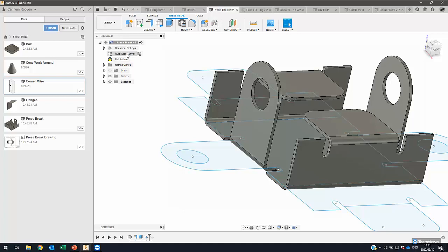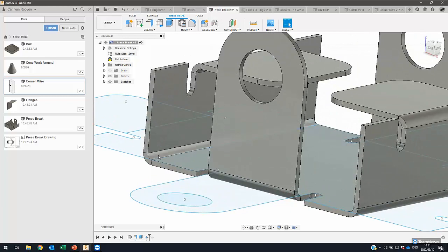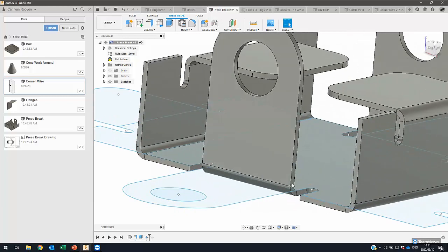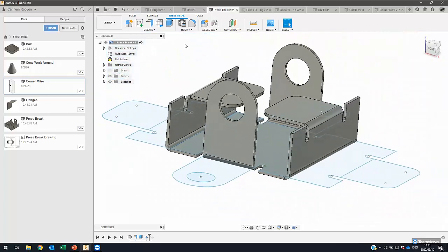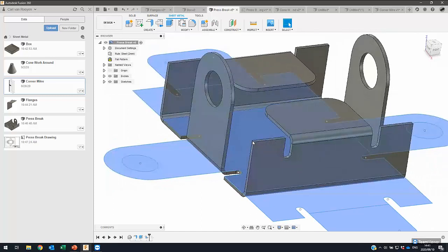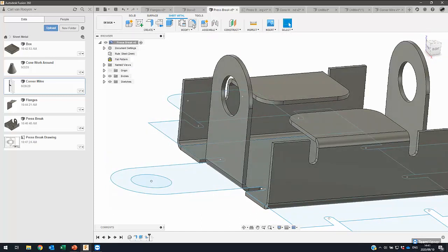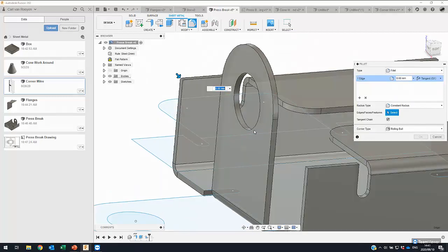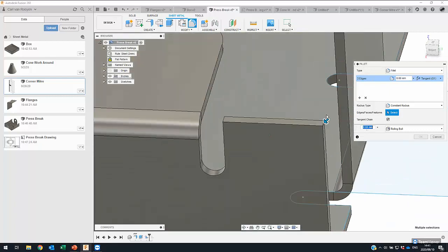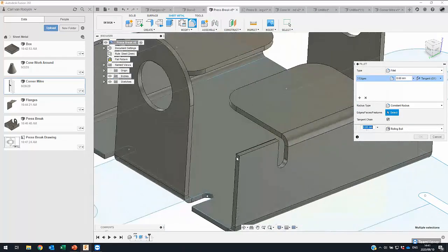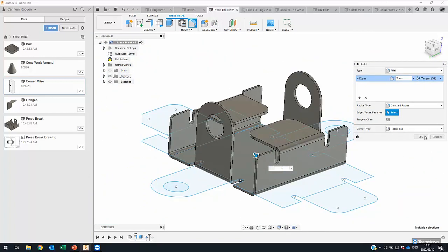Fusion 360 takes into account the K-factor and bending rules and the bend dimensions, as well as adding in any reliefs. So what we could do here is modify this by adding in any corner rounds. Let's go ahead and do some simple filleting and modify the existing part.